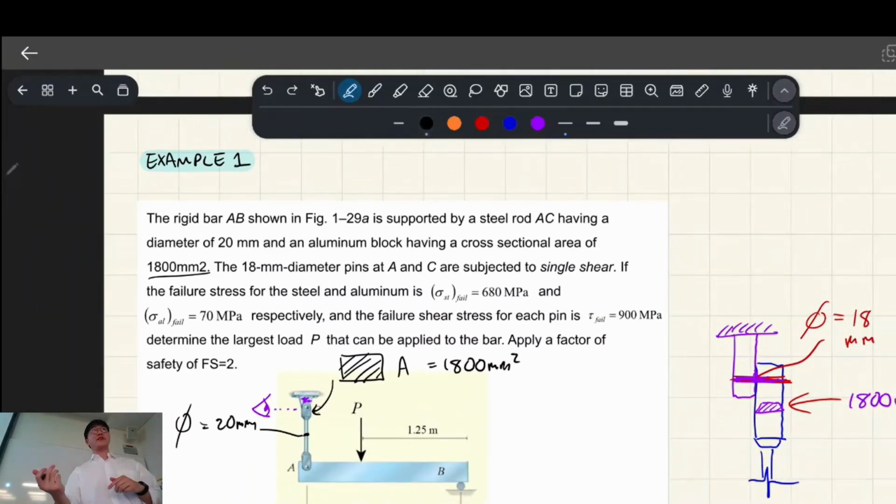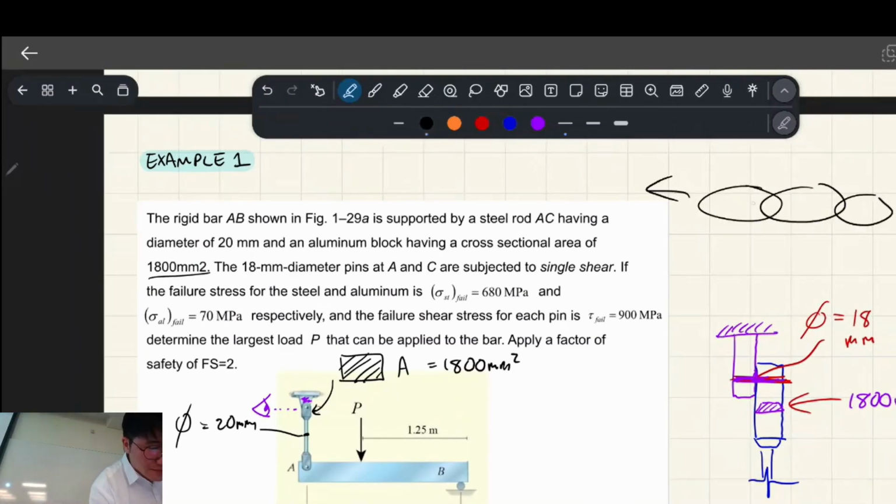And the first thing that breaks, imagine you had 3 chains, and you're pulling on them. These chains are made of different materials and have different cross sections. The whole thing is going to break once the first chain breaks. And that's basically what our system is. It's like a series of chain links. So whatever breaks first is going to govern what causes the whole system to fail.